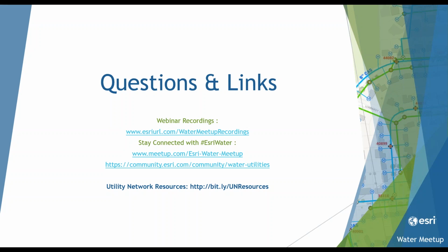Thanks a lot, Jason. We had a few questions about ArcGIS Online. Are customers able to run the UN in ArcGIS Online? So ArcGIS Online does not support the utility network at this time, meaning that it doesn't support the utility network functionality. It would be possible to register the feature services and expose those through web maps, but you wouldn't have really any functionality at this point for a utility network. It is something that's been talked about to be developed. I don't have a lot of information on that at this time. But certainly check back with us at a later date.